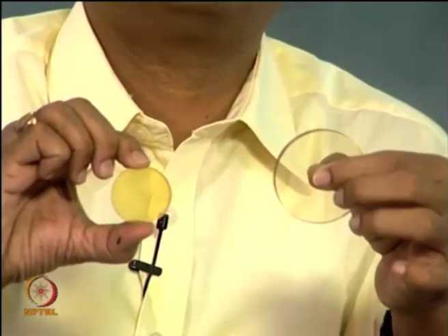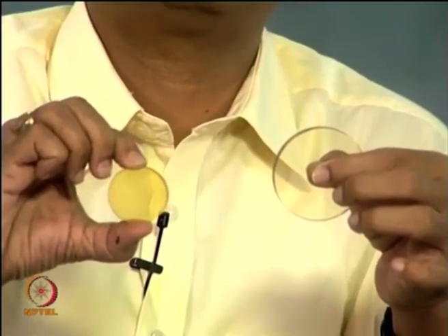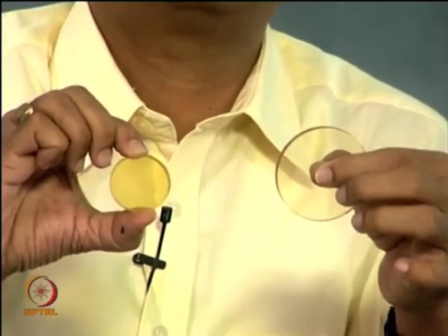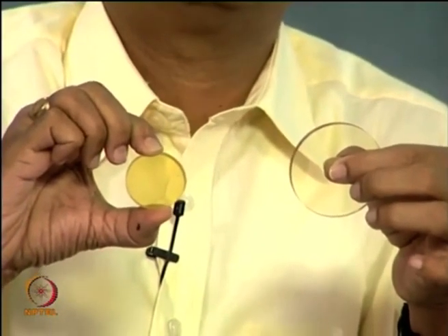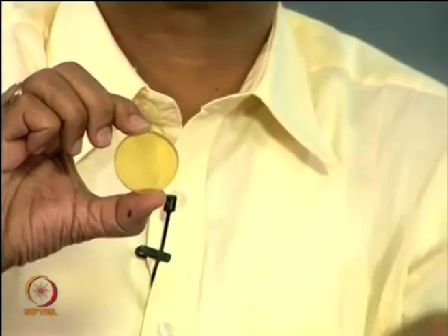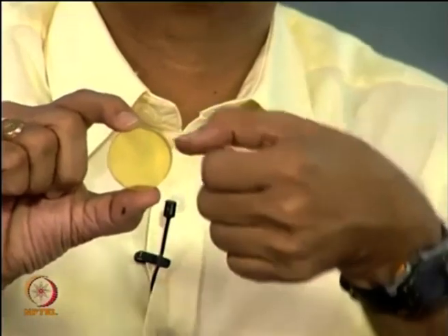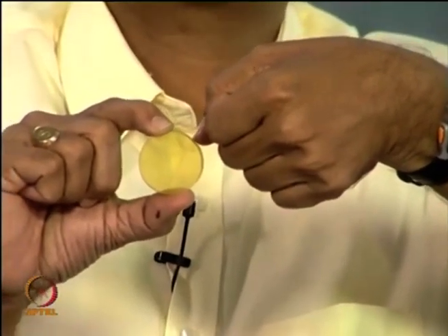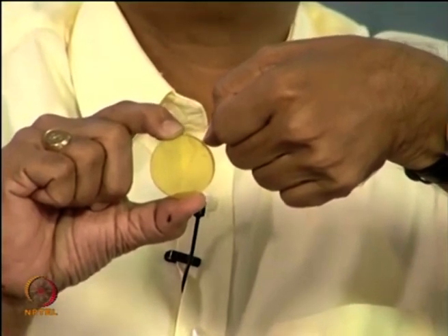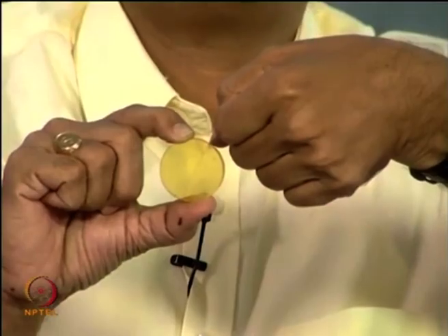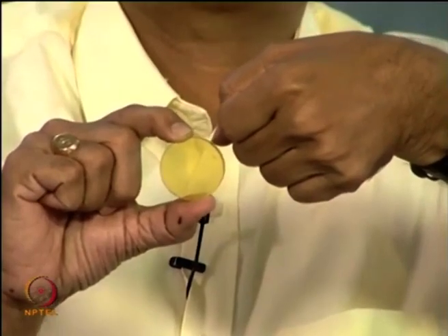You can see the deformation when it is compressed. You can see my fingers are pressing that, it is so soft. So, it is very good for models for class illustration, and also a good model to do the fingernail test. When I put the fingernail, it gets compressed very easily. So, I can find out the sign of the boundary stresses by nail test without resorting to any external gadget.